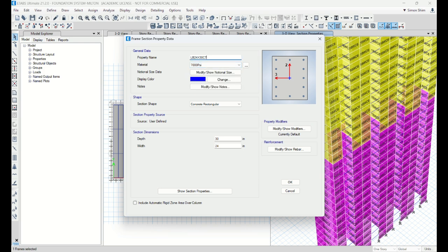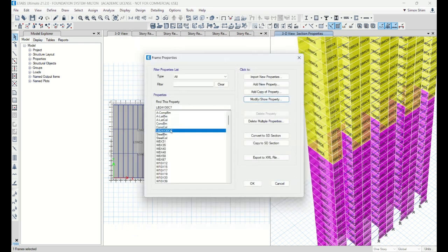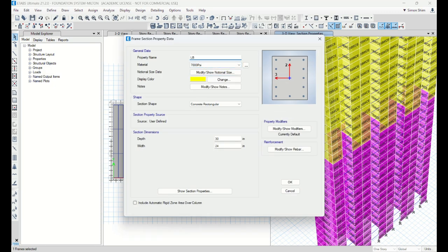So we're gonna adjust it, and then we're gonna create a few more link beams. Now wall thickness here is 18. I'm gonna keep the depth 30. In this case I'm gonna make 6000. So 18 by 30. See 6, right? 18 by 30.